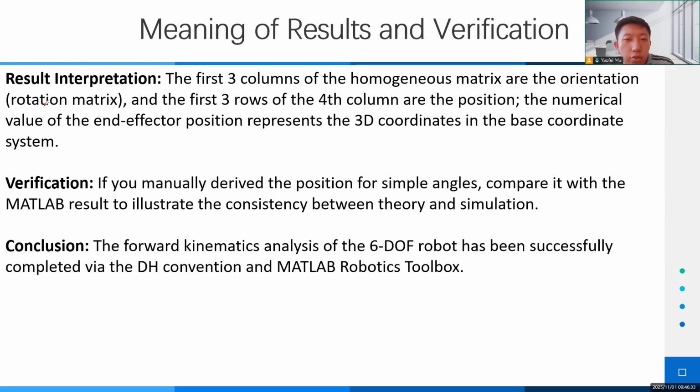To check if our results are right, we can do a simple manual calculation of the end effector position when joint angles are simple. Then compare this manual result with the MATLAB result. They match well, which means our analysis is correct.